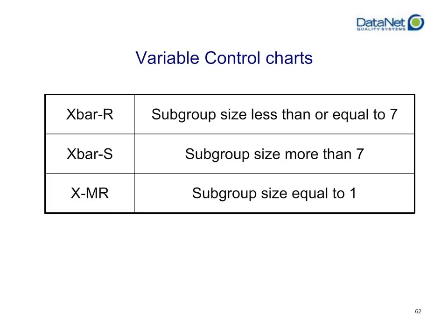Therefore, you need to have some sort of comparative statistic that you're going to use to show volatility for your secondary chart. And the way that we do that is by using something called a sub-range, where we define how many points back on a control chart, on an X and MR chart, you want to look back to do your comparative analysis. We will actually do an exercise with X and MR, so it'll become clearer as far as how that works. But you absolutely can have a subgroup size of 1 for a control chart, both just in general with SPC, but as well as with WinSPC.